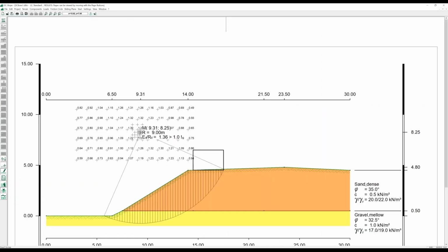We have a friction circle just going behind the building with a much higher utilization. The previous one was 0.8. So this is the critical friction circle spanning over the building with its high weight located on the slope. So if there are big jumps, for example, here we have a utilization of 0.8. Here we have an infinite safety. We can't cut the building. And on the other side, we would have just a high utilization.